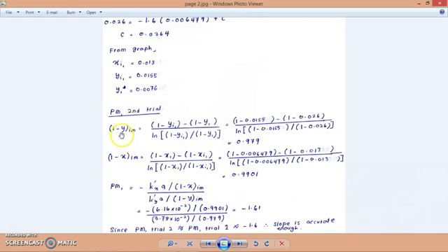So you have to solve for 1 minus yim and 1 minus xim, and these two equations we can get from the appendix. y1 and x1 are already in the question, in your material balance. yi1 and xi1 are from the previous values you got from the graph. So you can solve this equation, where 1 minus yim is 0.979 and 1 minus xim is 0.9901. Just substitute into the original equation for a packed absorption column, and you will get the value for the slope, which is minus 1.61.